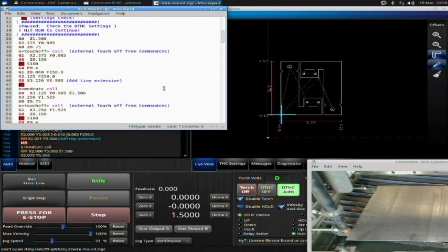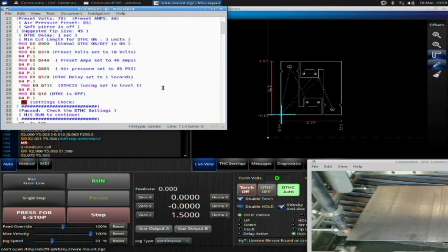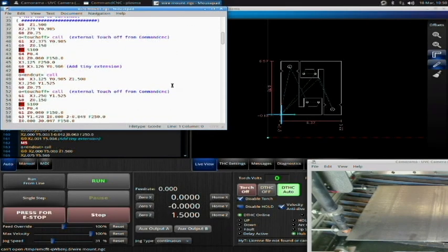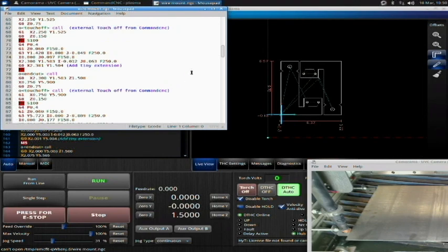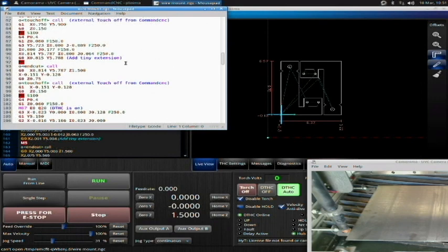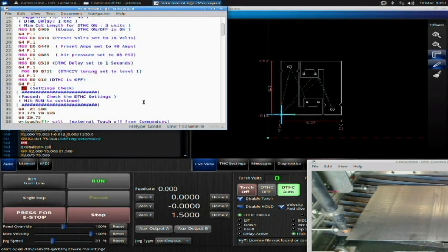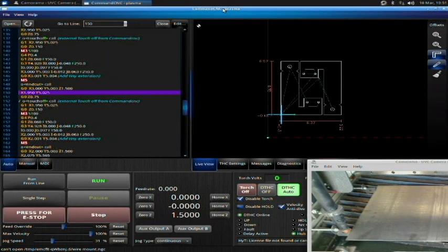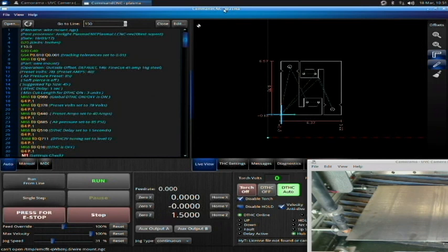Okay. I do not recommend you do this necessarily unless you know exactly what you are changing. If you properly set up your cuts in SheetCam, that's the best way to make changes. You know, because some people will say, well, I want to change my speed. Well, your speed is set throughout the code, and you would have to go through each individual spot and change the feed. You know, feed 250, feed 250. These would all have to be changed. You can't just go change one spot necessarily. Okay. So if you close this, the machine reloads the code to see if you made any changes.